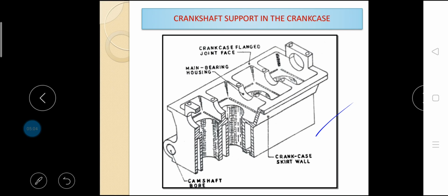The grey cast iron for the cylinder block usually has the composition 3.5% carbon, 2.5% silicon and 0.65% manganese. Carbon serves to provide graphite, which improves lubrication. Silicon provides wear resistance by forming pearlitic structure, while manganese increases the strength and toughness. A typical aluminium alloy for cylinder block contains 11% silicon, 0.5% manganese and 0.4% magnesium. Silicon reduces expansion and increases strength and wear resistance, while manganese and magnesium improve the strength of the aluminium structure.